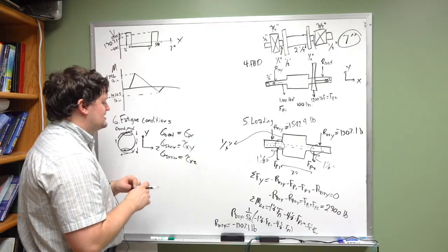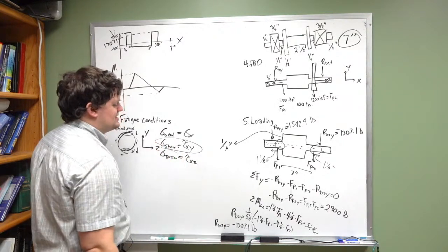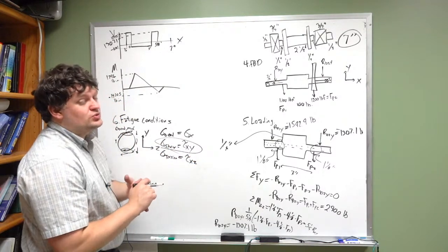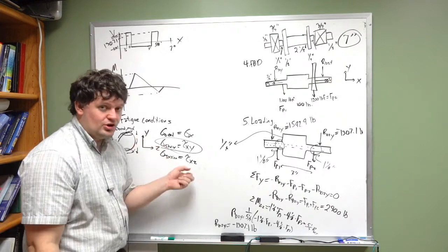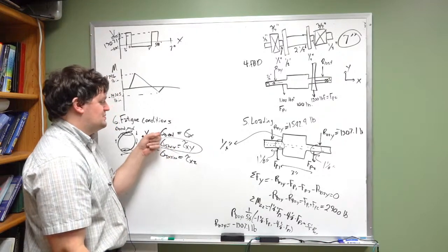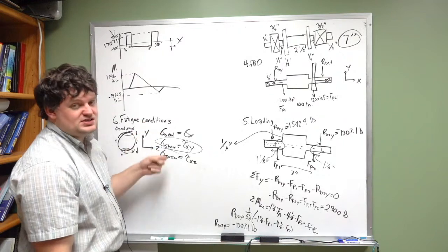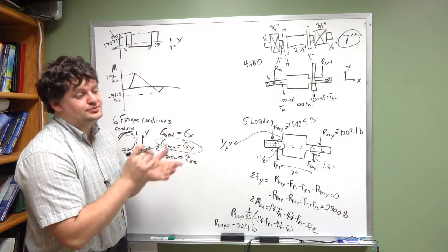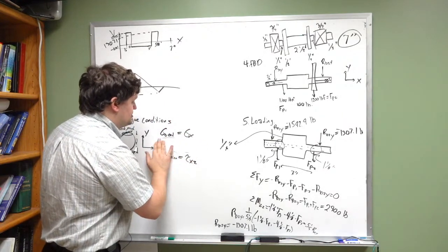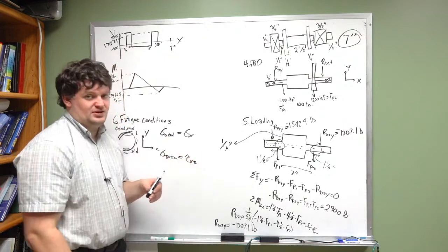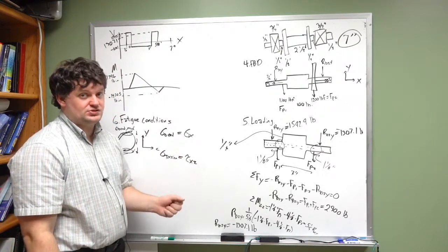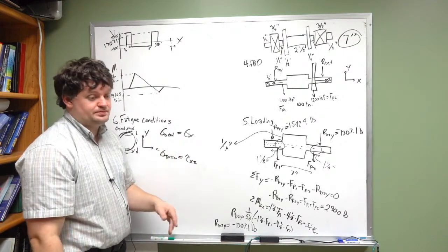Okay. One of the nice things about this is that shear stresses tend to be significantly smaller than the torsional stresses. So usually you can ignore the shear load stresses because they don't create as much stress as bending or torsion. Both of these tend to be a lot larger. So for this case, to simplify the problem, I'm going to ignore the shear stress that's due to shear loading. And we're only going to consider bending and torsion. This is going to create a planar stress condition for us, which is okay. It's not a problem.